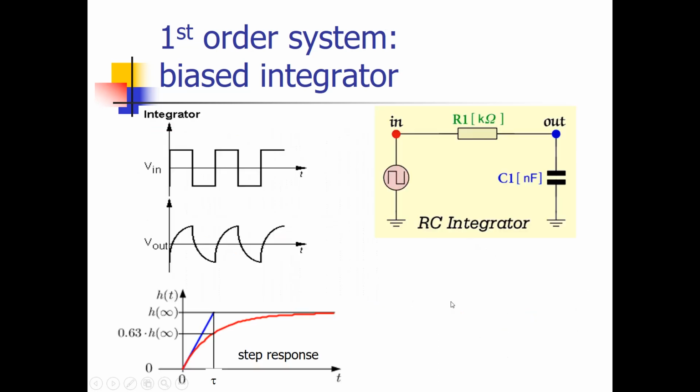Okay, we can also look into realization with analog components, for instance an RC network. When we put a step on an RC network, so a step on a first order system, and that is really important, the output of that first order system has an e-power curve, so to say.